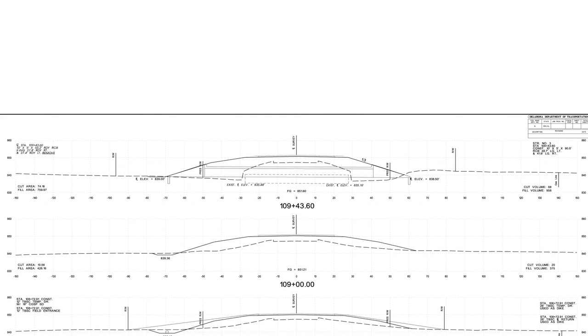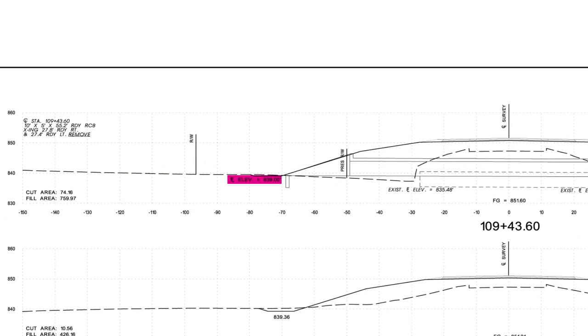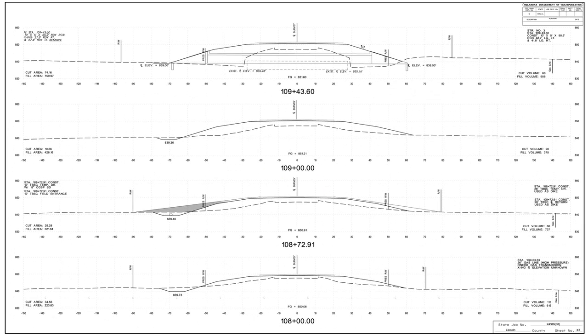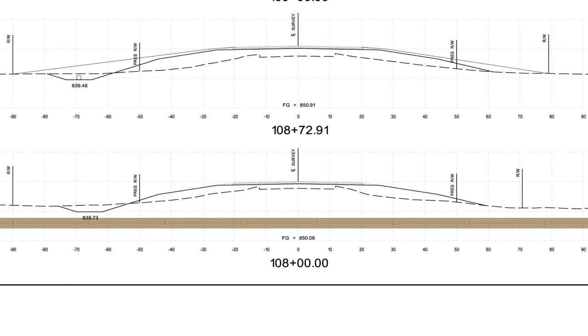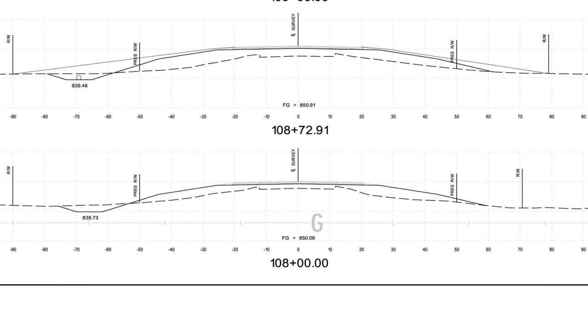Items which are depicted on the cross-section are existing or present right-of-way, proposed right-of-way, special ditch flow line elevations, driveways with notes, side drain structures with notes, existing cross-drain structures with notes and flow lines, and proposed new cross-drain structures with notes and flow line elevations. Crossing and parallel utility notes and labels are also shown on the cross-sections.